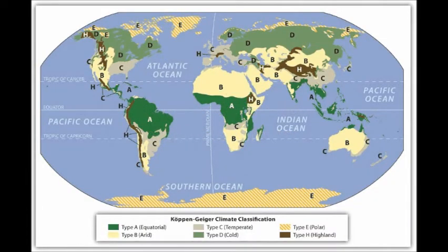A temperate climate lies between the two areas that the design was proposed. Therefore, the passive strategies will be in common with the rest. Direct gains and sunrooms are highly recommended for such climates because they too have cold winters. However, the shading devices have to be carefully calculated so they can bring in radiation during winter and keep it away in summers. Night insulation can also be a good strategy to be used for temperate climates.